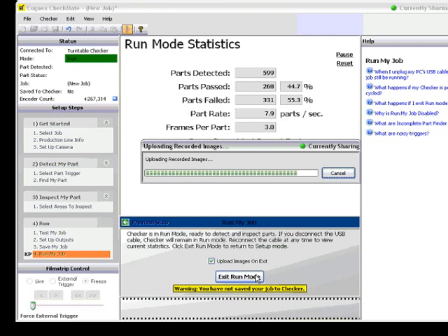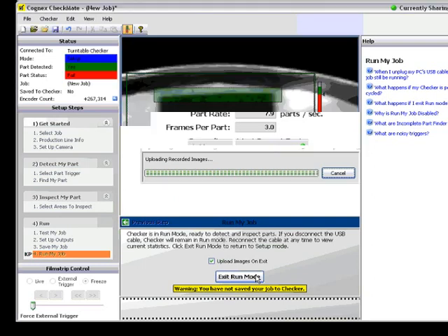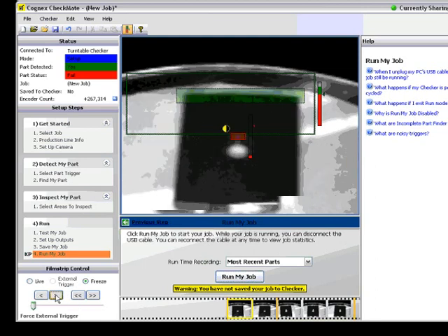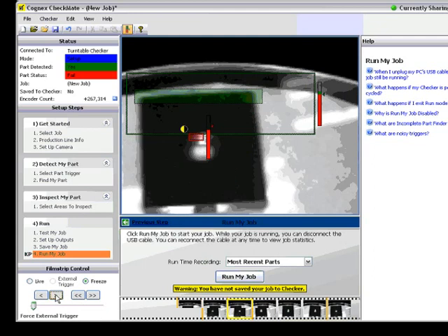I should be getting 50-50 here. I obviously got some part that's not being detected correctly. Well, this is where that film strip really comes into play. So I'm going to go on through the film strip, and you see that there? That is actually a threaded part that the box is just off-center to where it needed to be.